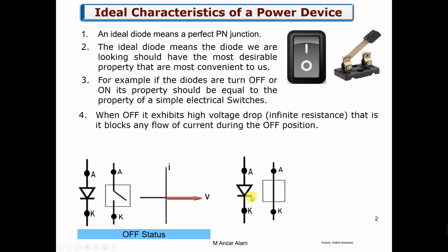There is no barrier voltage, there is nothing. So if the diode is on, and for an ideal diode, we assume that from anode to cathode there will be a complete conductor as for this one. And if this is a copper wire, a complete conductor, what will be the resistance at anode and cathode? There will be no resistance. We are assuming that this is a pure conductor. So ideally, if the diode is on, the resistance from anode to cathode should be zero.